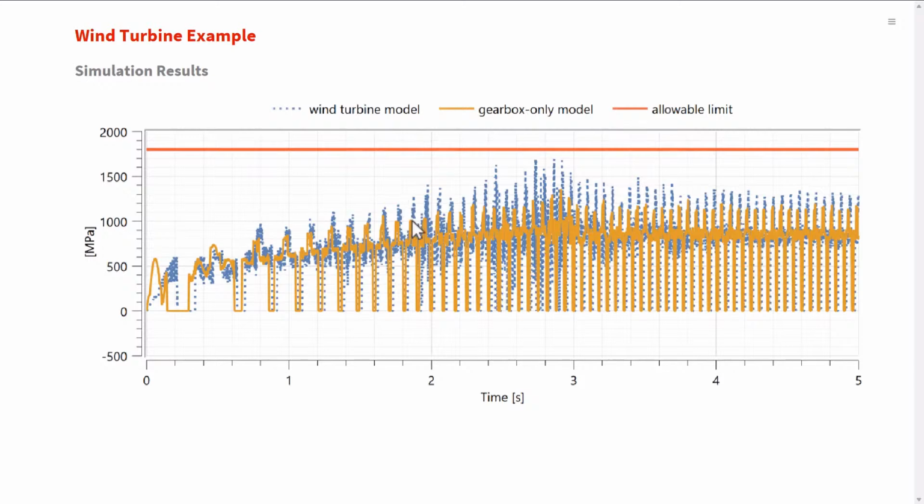And in both cases, we only plot the planetary gear contact stresses, not the three-stage gearbox, because we observe the maximum stresses there. Just a glance is enough to tell us that the contact pressures are now getting closer to the allowable stress limit with the 1700 megapascal. Still, despite this, our simulations indicate that we are fortunately still within the safe boundaries.